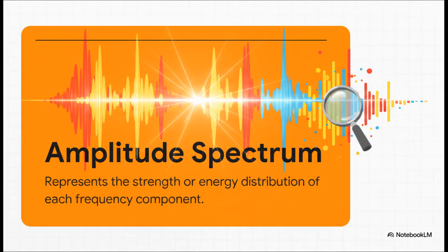So, to put it formally, the amplitude spectrum represents the strength, or the energy distribution, of each frequency component. Meanwhile, the phase spectrum represents the time alignment, or the phase delay. The really crucial takeaway here is that both of these matter immensely. In fact, and this is a huge deal in engineering, phase is absolutely critical for modern systems. If you've got phase distortion, your high-speed digital communications simply will not work. The timing of the data packets will literally collide with each other.